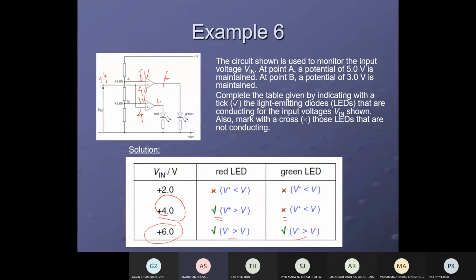When positive 6, when both light up, maybe we can indicate that the temperature is getting even higher, as a detector. So the input must be from a sensor. If you check temperature, the input must be a thermistor connected to another resistor in a potential divider method.